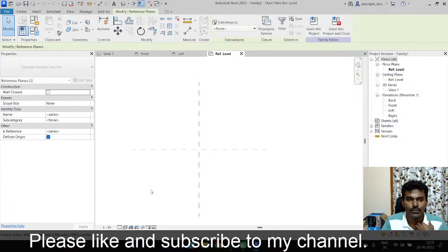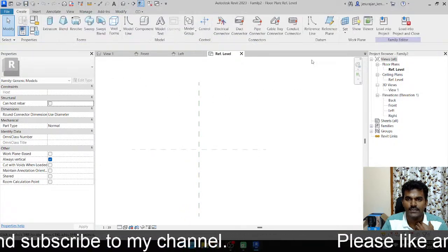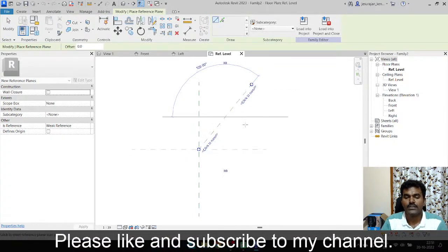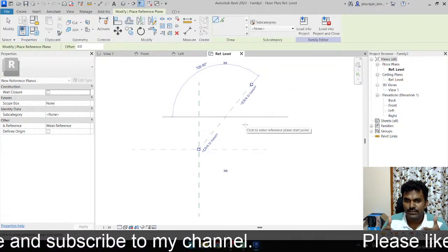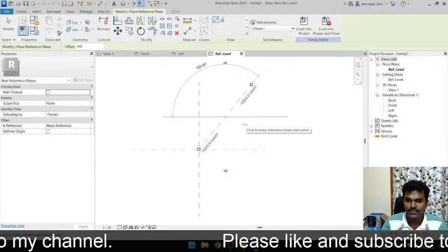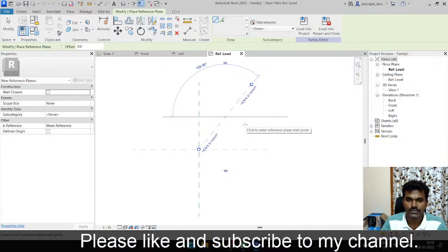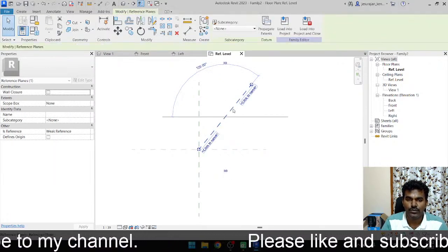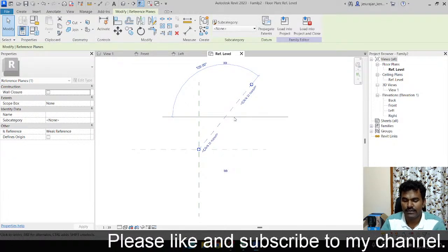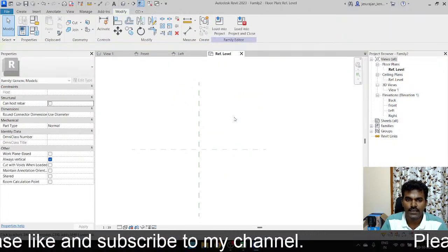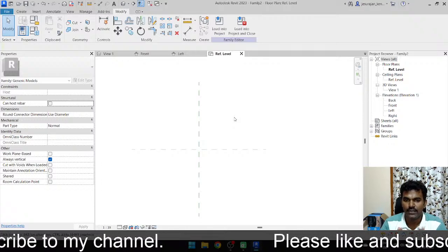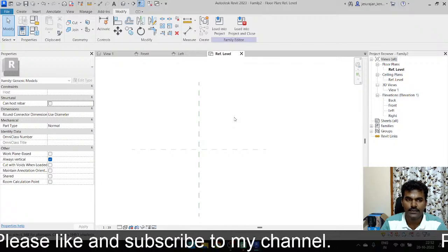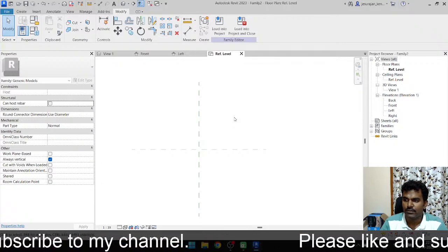So this is a center point. Here I'm going to take a reference plane and take the center point. If we are modeling it as a door, that means we are supposed to open the door, right? So I'm going to make that door with a swing angle, so that whenever we change the swing angle, it should look open, closed or half open. That kind of adjustable swing I'm trying to make.